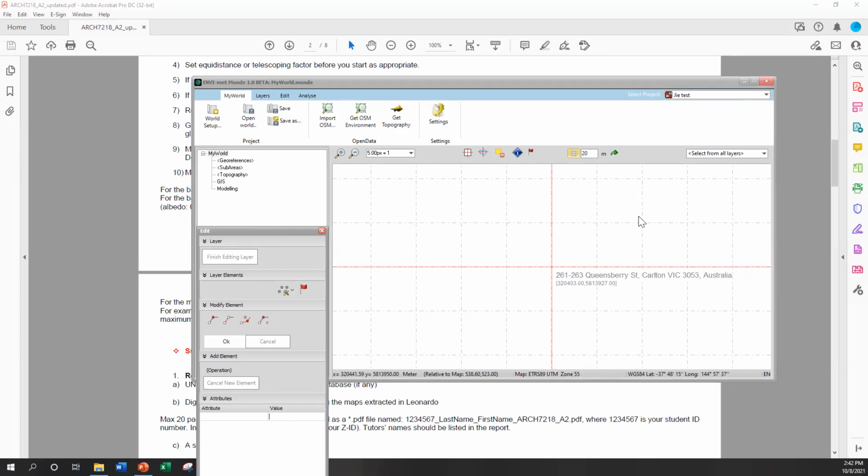Once you have created your model, you need to use this Envi-met guide to set up your simulation. You have to identify which day of the year you want to simulate, how long the period you want to simulate, and what the boundary condition and initial condition are. If you get stuck, you can just unmute yourself and let me know. The weather condition of the simulation period, you have to specify in the Envi guide, and then we use Envi-core, which is a physical engine, that will help you calculate the physics in your model. And then, if you want to add some comfort features, you can.